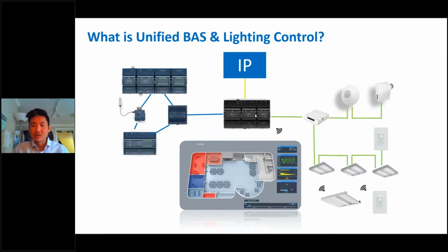Right now, there are manufacturers that offer both the HVAC controller and the lighting controller that allows you to talk BACnet, and that is the bridge that you need to create that single pane of glass that Chase was talking about earlier. Because those two controllers are developed together, you know that the lighting side and the HVAC side will talk to each other, and it will function the way that you had intended it to function, and reduce some of those conflicts and increase comfort levels.